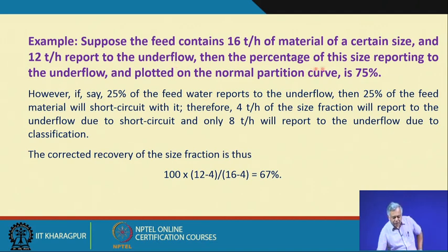Then the percentage of this size reporting to the underflow, based on this conventional analysis: you are feeding size x at a rate of 16 tons per hour, and out of that, 12 tons per hour you recover into the underflow stream.